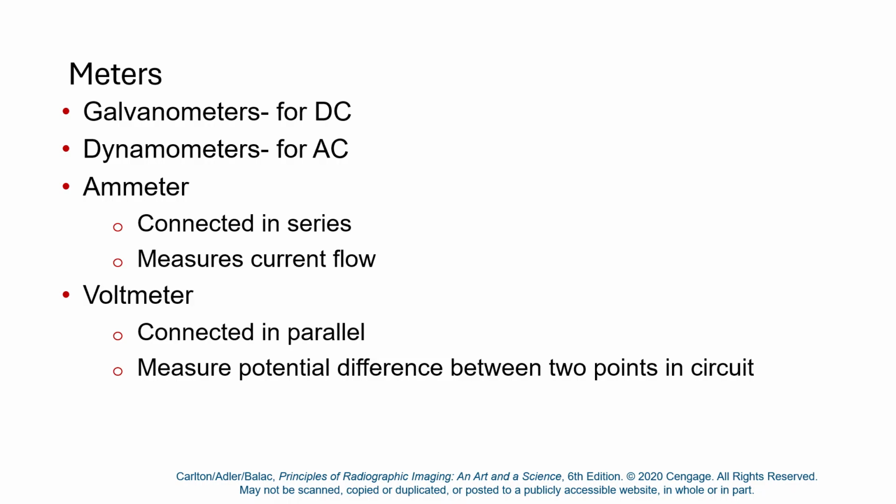That'll be very handy in answering if you remember those two principles. You're going to get a diagram of the schematic, and it's going to have a voltmeter and an ammeter, and you have to tell which one's which. Well, which one's wired in series? The ammeter. Which one's wired in parallel? The voltmeter, for the same reason.